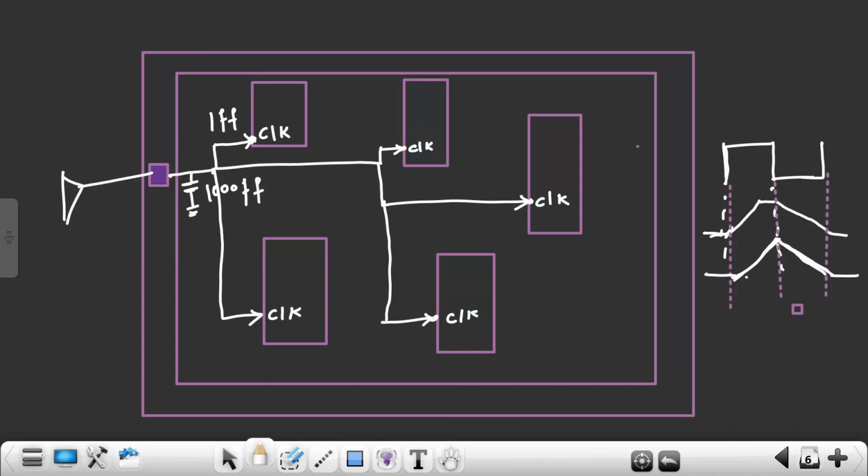This may be because of two reasons. One is pin capacitance. This clock port is directly connected to all the cells which have high pin capacitance, and this pin capacitance will lead to high load capacitance. The second thing is net capacitance. For example, for this flip-flop, you have more net capacitance. Even this net capacitance is going to form a huge load. So charging and discharging will not happen in a short amount of time. It will take a huge time.